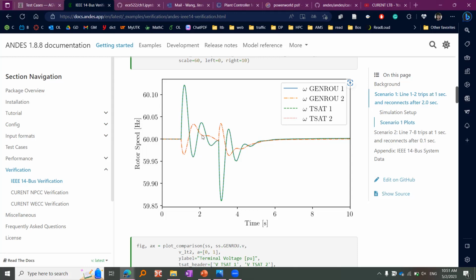The reason you have to do that is that if it's a constant power load, once the voltage drops too low, the currents are going to be too high. You're going to have convergence problems, and it's not realistic either. If I've got a very low voltage, my load is no longer constant power. It's not going to just keep drawing more current. But those types of things are not explicitly modeled.